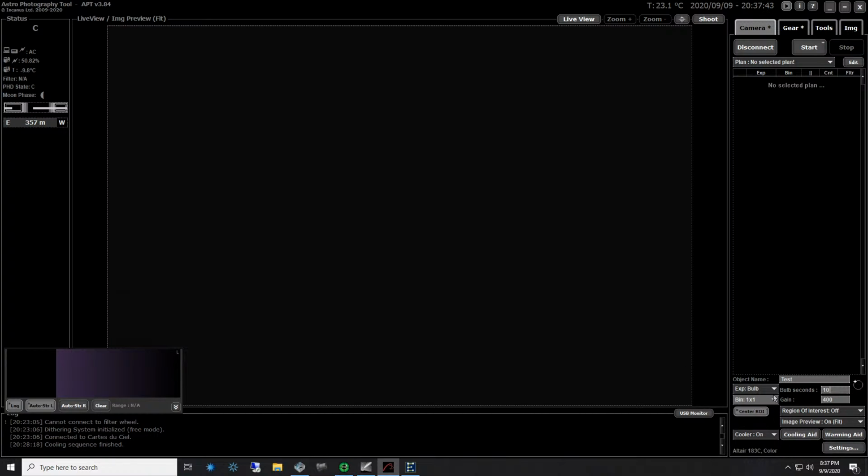I can set the binning. I've heard it pronounced two ways, binding or binning, and what that does is group the colored pixels in the camera, so that instead of taking one set of red, green, blue pixels to make a picture, they use a group. A 2x2 binning would use 2 across and 2 down, so 4 sets of the red, green, blue pixels. It gives you a bigger coverage, but the definition isn't quite as good.